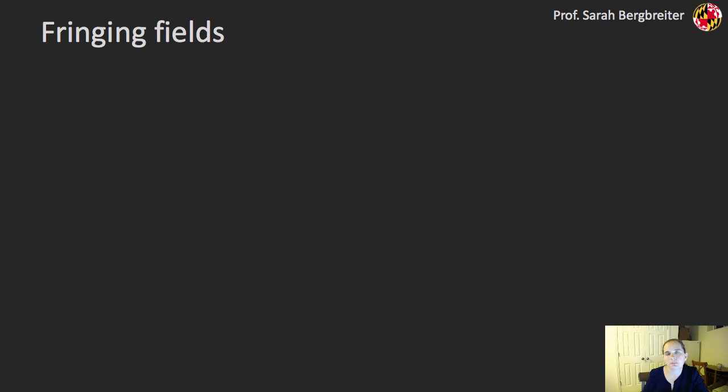Despite the ubiquity of these parallel plate sensors, which go into a lot of the inertial sensors we've talked about, a number of humidity sensors, and soil moisture sensors, what you probably interact with most commonly that's a capacitive sensor is a touchscreen. This is a slightly different setup than a parallel plate, and unfortunately it's really challenging to model, so we're just going to talk about this qualitatively.